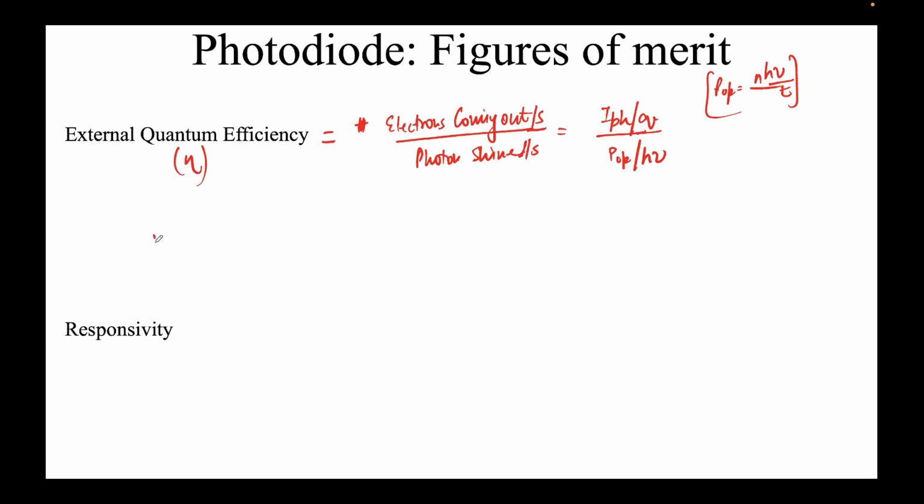There's one more thing called the internal quantum efficiency. That essentially means electron hole pairs generated per unit second, divided by photons reaching the depletion layer. You'd ask why photons will be lost. Please remember, as we have already talked about, there is a P plus stack, or P stack, sitting on top. It will absorb some photons that are coming on the surface.